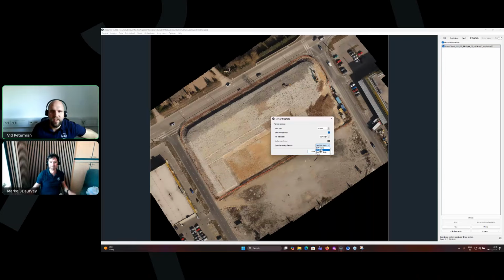in the correct position. And lastly, we have this little trick in here. If you have software that does not support reading the georeferencing information from the World file or GeoTIFF, you can also create a DXF frame. The software will draw a rectangle in which you can then import the image. Okay, cool. So also in standard AutoCAD you can bring it in. No need for AutoCAD Map and Civil 3D and everything like that.